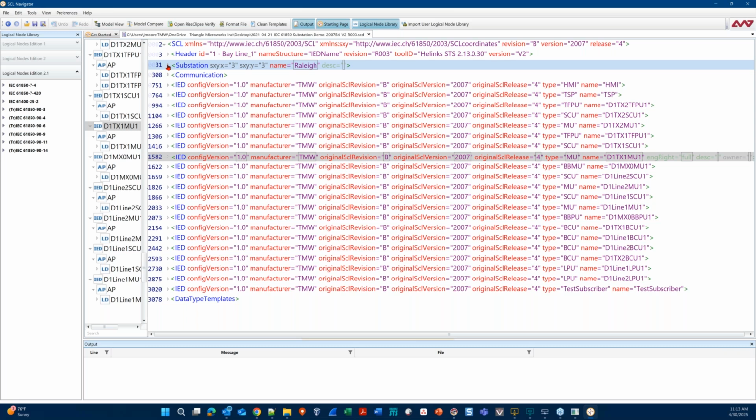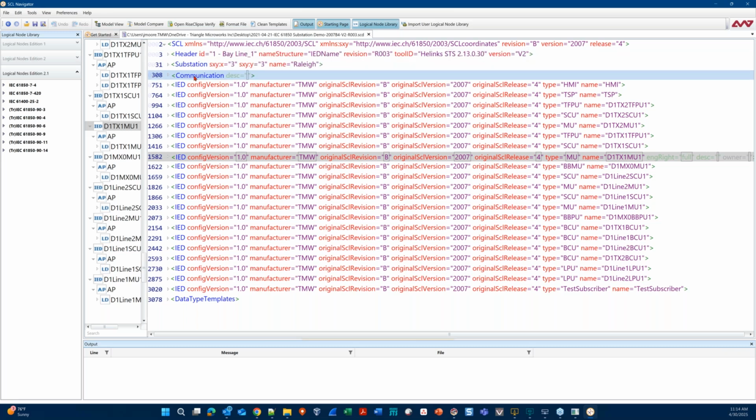Moving down into the substation section, this is commonly created as part of the specification stage, and you can actually put topology information about your substation, what breakers and switches are present, who's connected to what in a physical system. The communication section down below, this is where we're going to have all of our IP addresses, VLAN IDs, any communication settings.